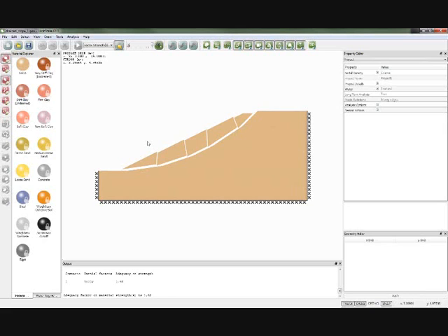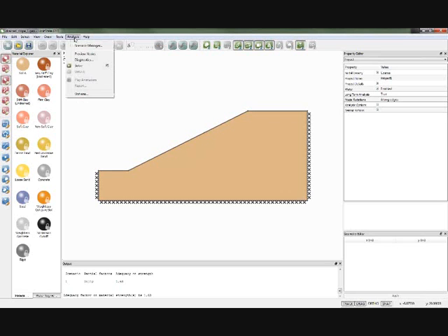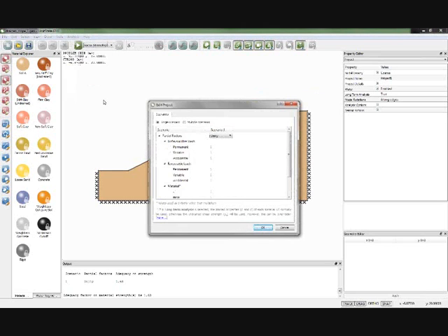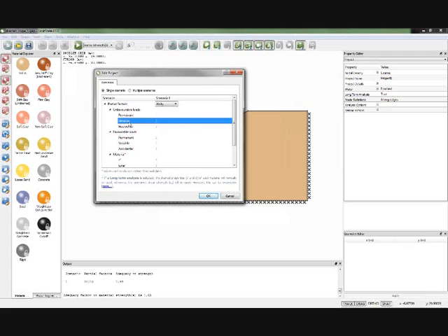Now, if we want to apply safety factors to that, we could say that's a factor of safety of 1.63 on strength for the whole slope, and be happy with that. But if we want to apply that to Eurocode 7, then we could use a scenario manager, and that allows us to set factors on unfavorable loads in the system, favorable loads, and material properties, c', tan phi', and cu. And we can set those to any value we want. Just to illustrate effectively what we're doing, if I click on user here, I change these values to